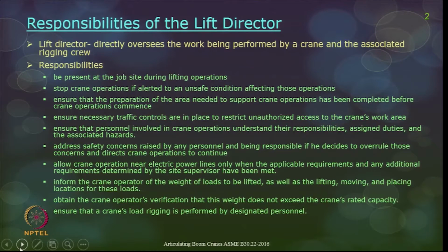His responsibilities: he should be competent and present at the job site during lifting operations. He should stop the crane if any unsafe situation is seen on the site, and ensure that the preparation of the area needed to support the crane operations is completed before the crane operations commence. He should also ensure necessary traffic controls are in place and that the personnel involved understand their responsibilities, know what they have to do, how the signals are communicated, and what the different hazards are. He should communicate this clearly to everyone.